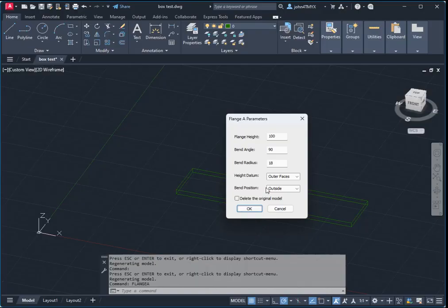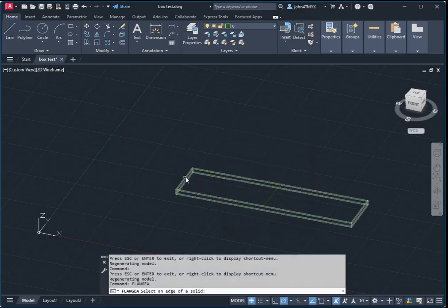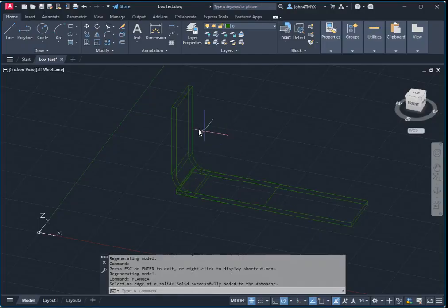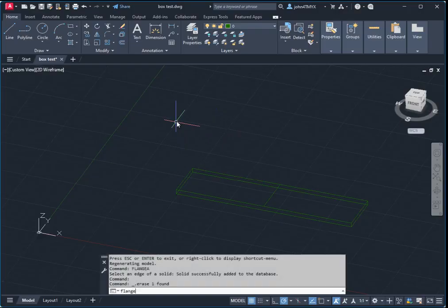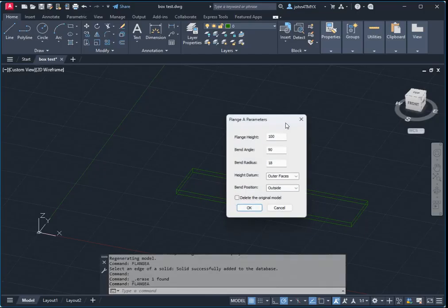There are detailed descriptions of how to use it here. Basically, it is used to define the baseline for the flange height relative to the thickness, and relative to the original shape of the plate. Click OK, then click here, and you can decide the shape you want. For flange A, for example, you can choose an adjacent edge and click OK.